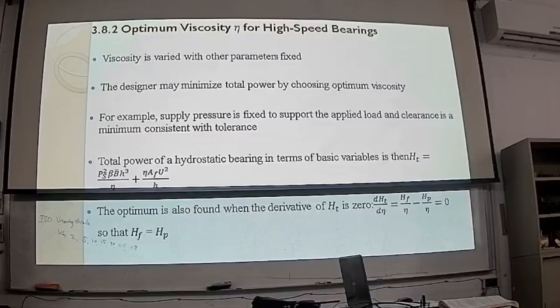It's not always that you can find an optimal viscosity. And usually we take a reference from the commercial product from the market. The main concern is rotational speed and pad area. That will decide your viscosity number for your application.